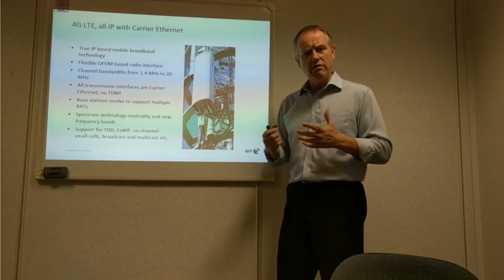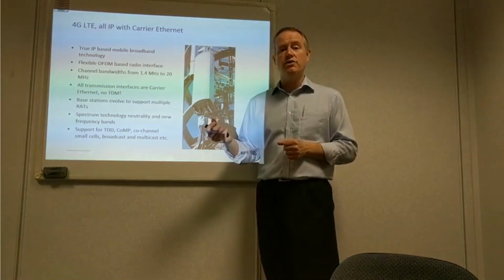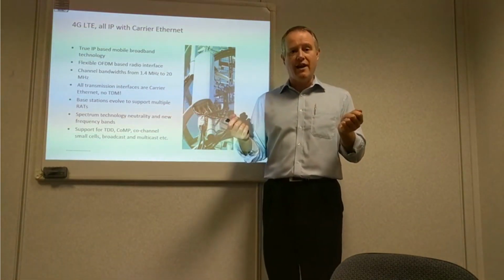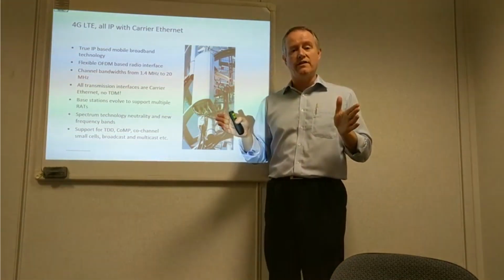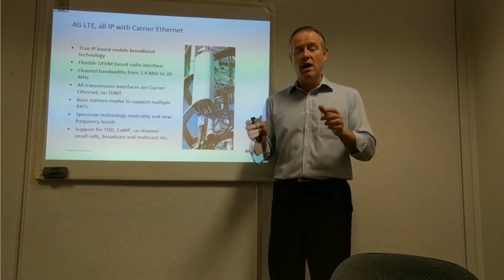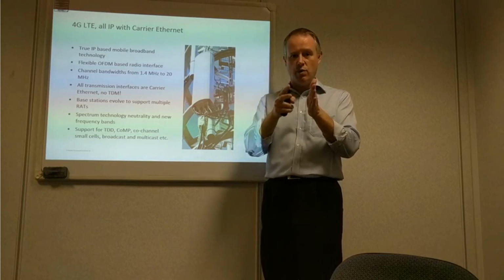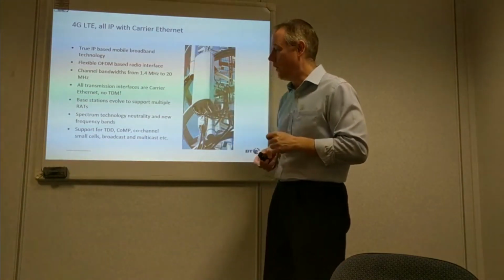So a whole range of new requirements now that not only need frequency synchronization, but also require phase alignment or time alignment, where effectively, if we visualize it as two sine waves, rather than having two sine waves on the same frequency, we need two sine waves that are not only on the same frequency, but start at the same instance in time. So 0 degrees, 90 degrees, 180, 270, 360 is completely aligned as that sine wave plays out.